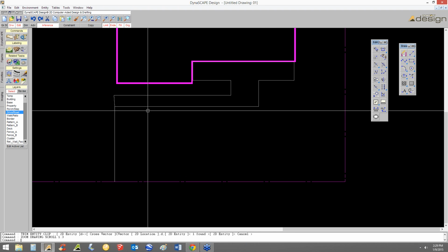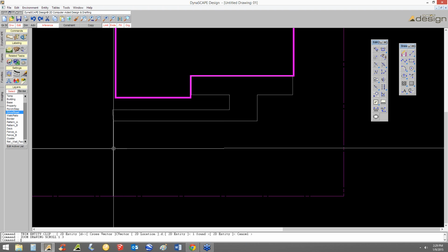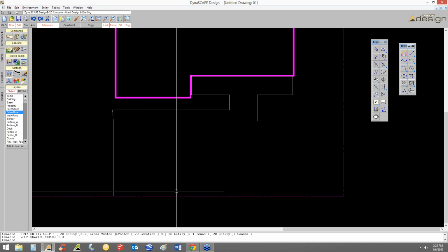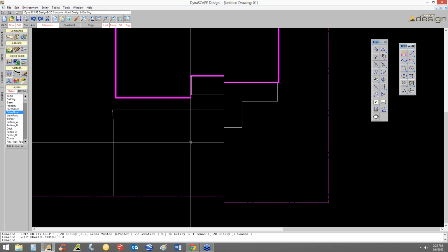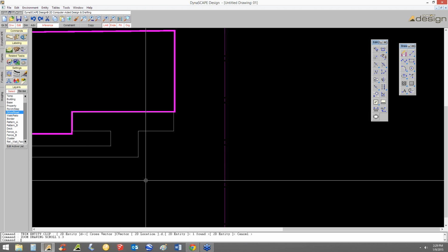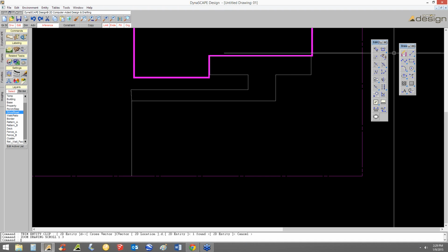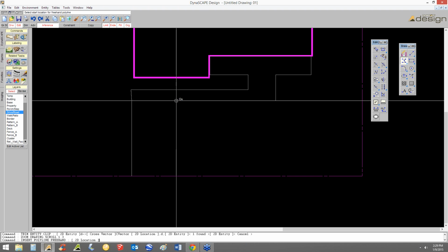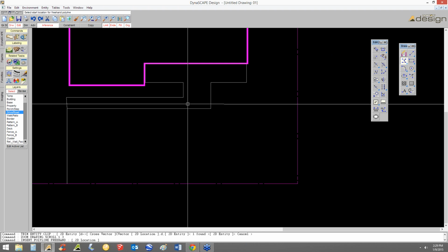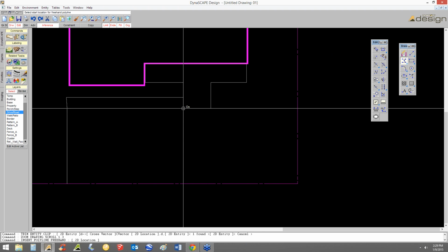Let's say we want to put a bed, you know, the normal bed you put kind of on the corner, but let's make it bend out, give us a nice area for a tree here. And then maybe we want to come off of this with a bed that curves around to the side of the house. So if you hold down the Polyline tool, it goes to this one that says draw a freehand polyline. So if you click on that and start here, and this takes a little practice. You'll pick up on it really quick.